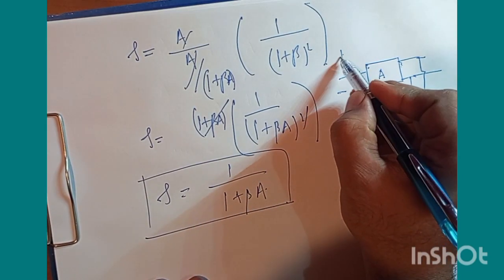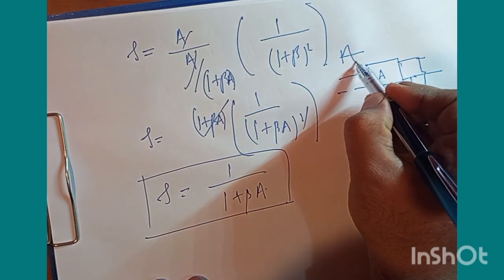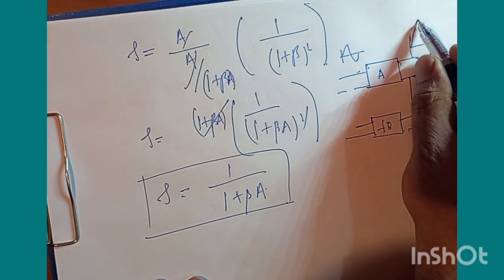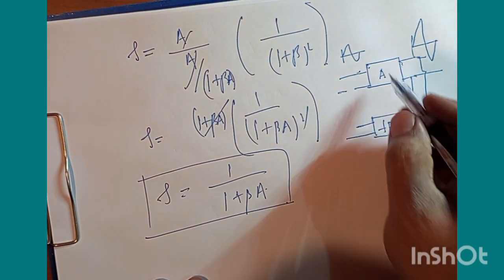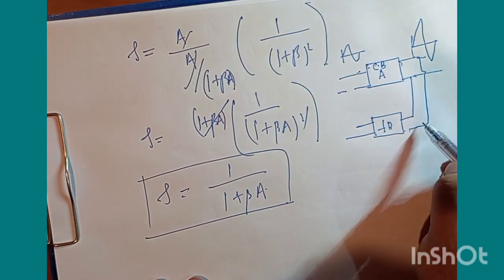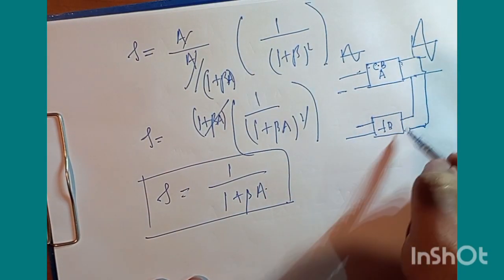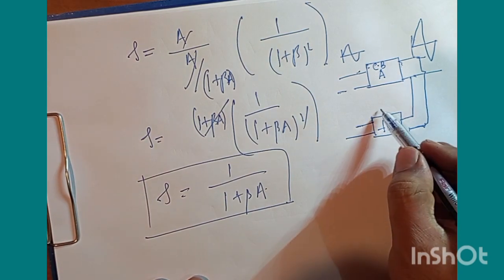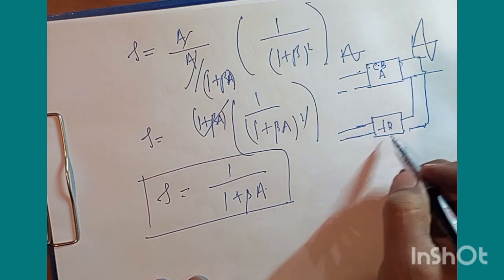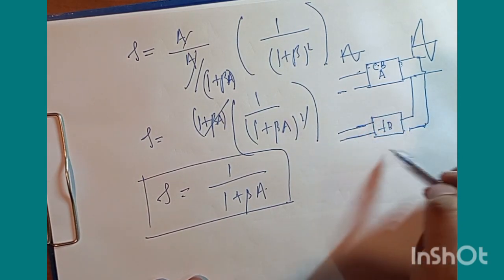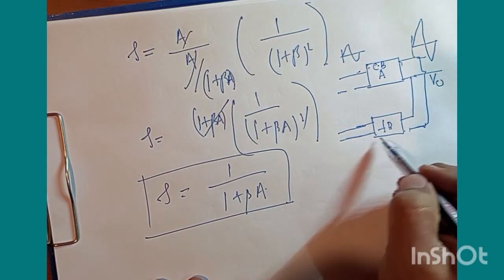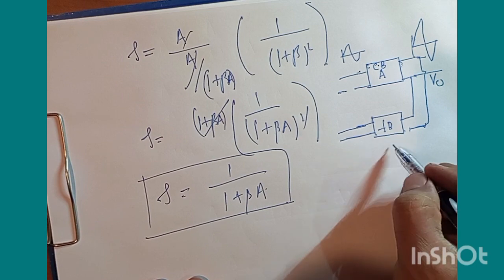So if this signal was having a phase like this, through the amplifier its amplitude goes up, and we make use of a common base amplifier here. And then we subject this output back to the feedback circuit. What the feedback circuit does here is it changes the polarity of the output signal by 180 degrees.